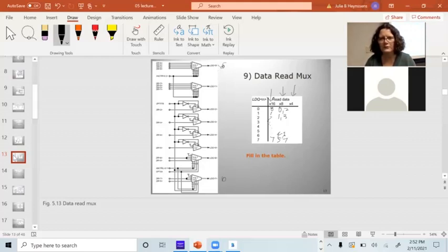If I go to a times 4, I'm going to have to read 4 out at a time. I'm going to have to make 4 reads of this to get all 16 bits out. The 16 bits are going to be loaded on these lines, or half of the 16 bits are going to be loaded on these lines, and they'll be read out either all at once, in 2 clock cycles, or in 4 clock cycles.